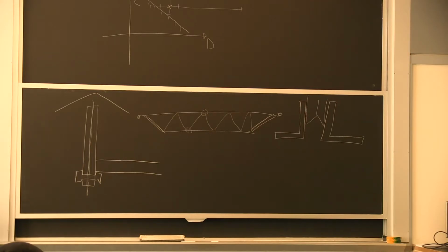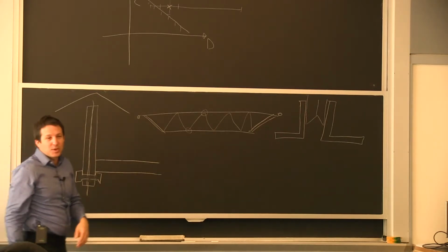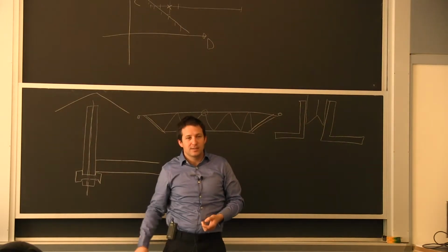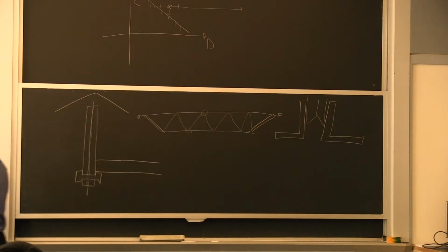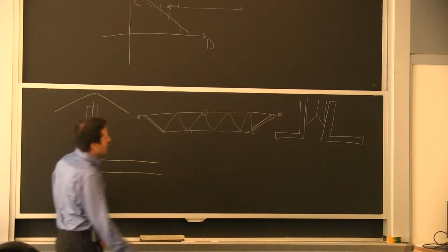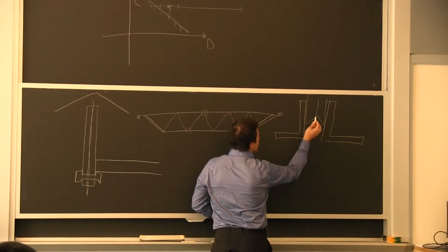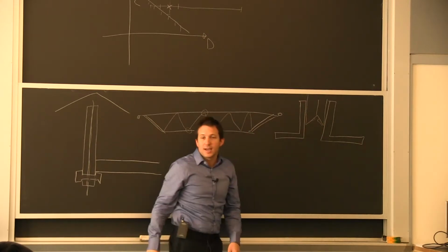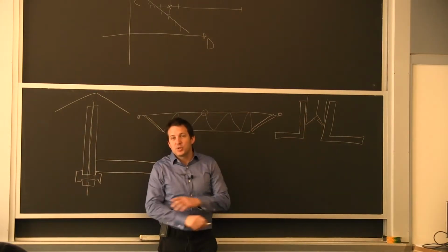These welds are extremely difficult to make. We were talking about the flare bevel detail. Now you have a very, very hard access, so it's hard to make them reliable. The good news is they're doing both sides. So if one of them is incorrect, the other will be able to take all the load. But it's completely confined. You have to come from underneath to do the welding on this leg here and on this leg. It's a very hard access. Yet it's the cheapest way to make them.